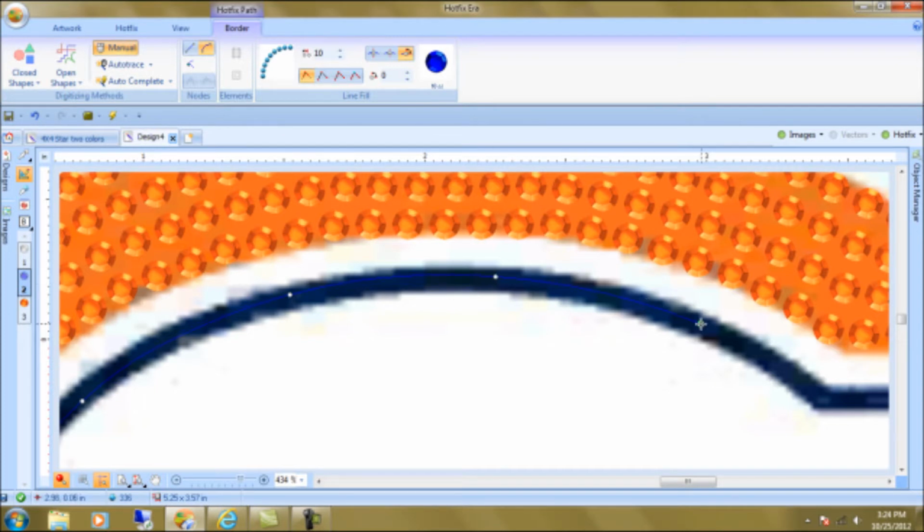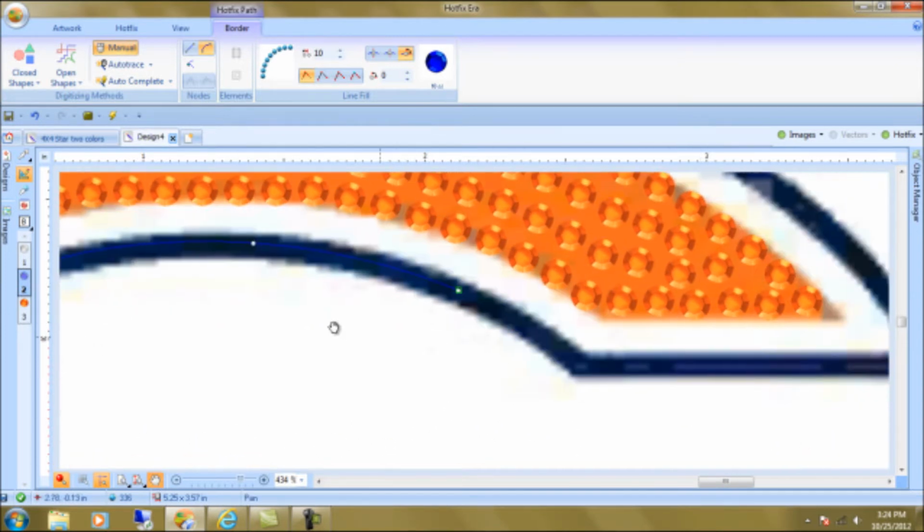Because I do want to finish this design today, but I do put quite a bit. I maybe put one every 2 inches, or every half or quarter inch. Again, we have this area where we're going into a straight line area here, and I need a corner node here too, because it does cut a corner here. So again, that's Control and Shift, and then click, and then I'll release my control button, because all I need, I'll hold my control button, and I'll place another corner node here. And it allows me to come out of this without flaring out on my curve.